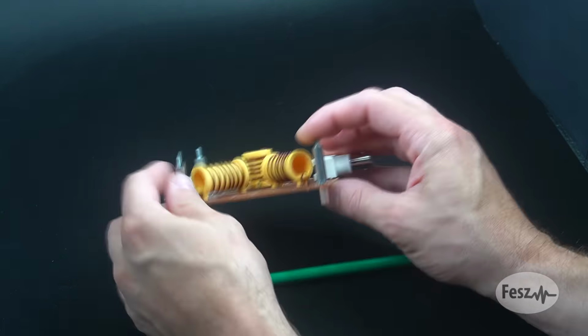So this was not an artistic choice, but rather a technical one. This practice is quite common in various devices, like this CB radio. To verify the filter's performance, I connected the 2 ports of the VNA to the filter and performed an S21 measurement. So there are 2 main things to look at.